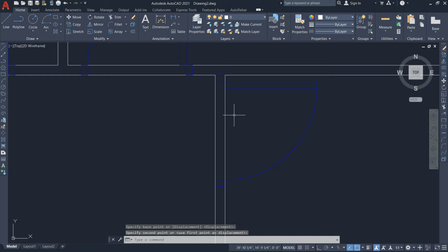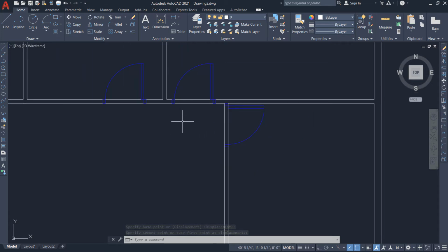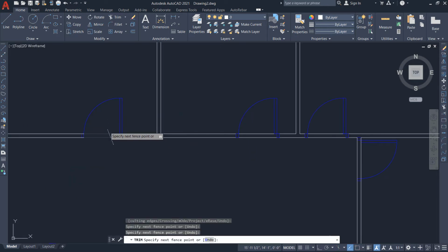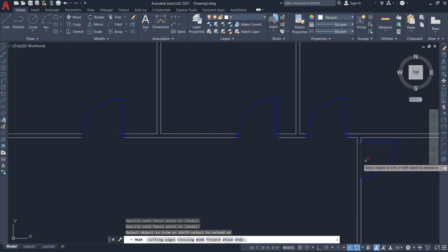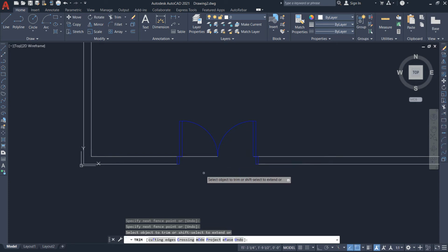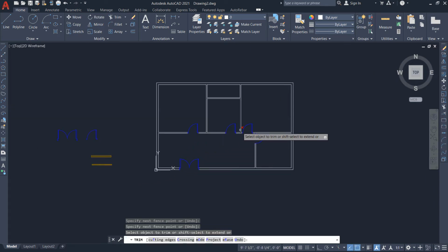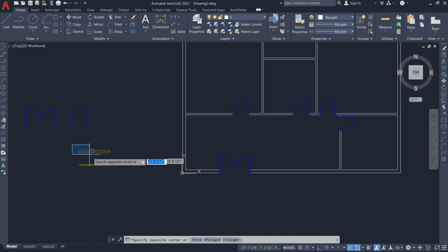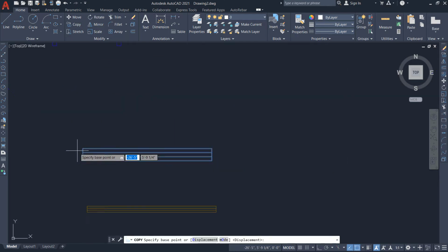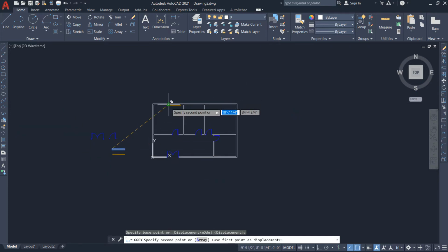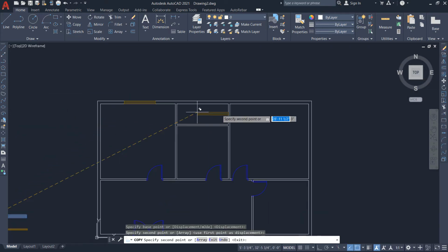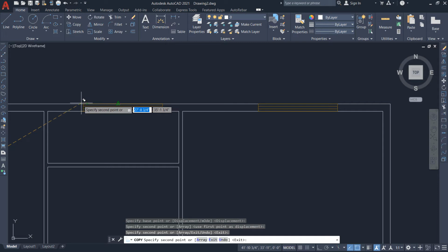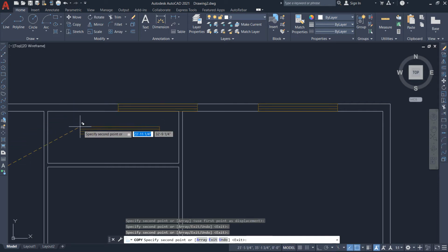Okay, so now to clear the geometry, I will again click trim, tr, enter. Okay, now it's looking good. Now I will put the windows in the wall. Okay, for 9-inch wall, copy, one window here, one window here. In the ventilation side,